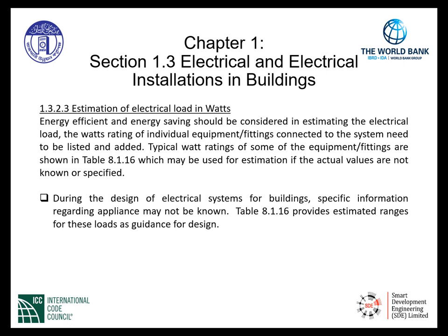Section 1.3.2.3, Estimation of Electrical Load in Watts. Energy efficient and energy saving equipment could be and should be considered in estimating the electrical load. The watt rating of individual equipment fittings connected to the system needs to be listed and added. Typical watt ratings of some of the equipment fittings are shown in Table 8.1.16, which may be used for estimation if the actual values are not known or specified.